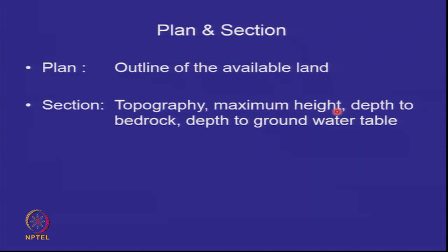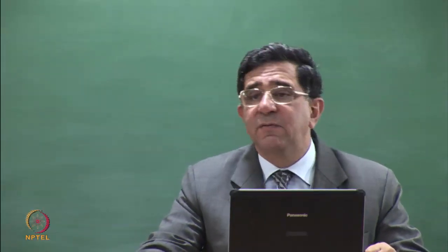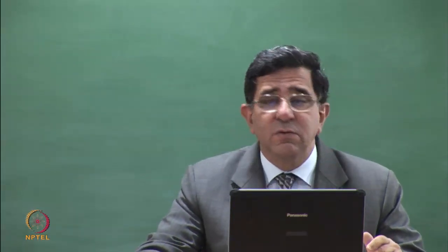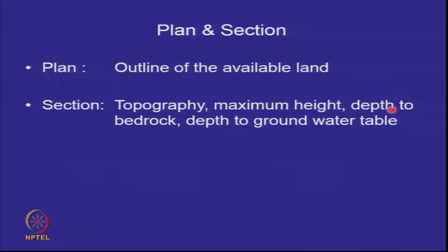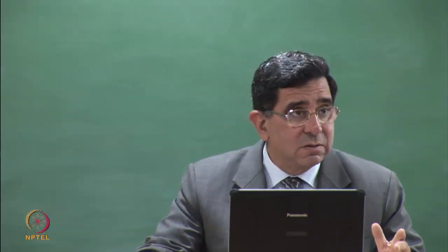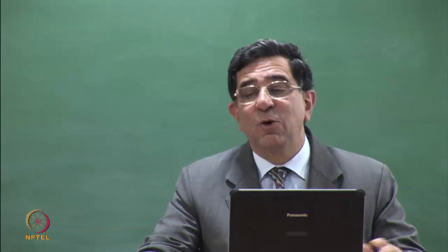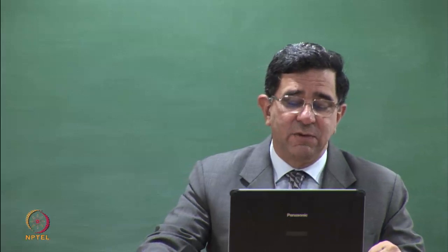The maximum height we would like to go to is a height which does not create a very huge visual impact. And I have said this earlier that 15 meters is a good height which we typically adopt. So we will know the height of the landfill. Depending on the depth to bedrock and depth to groundwater table, we will have an idea of the depth of the landfill. However, what the section will look like will also depend on the topography. Is it flat ground? Is it sloping ground? Is it low-lying area? Is it a valley? So that will determine the section of the landfill.